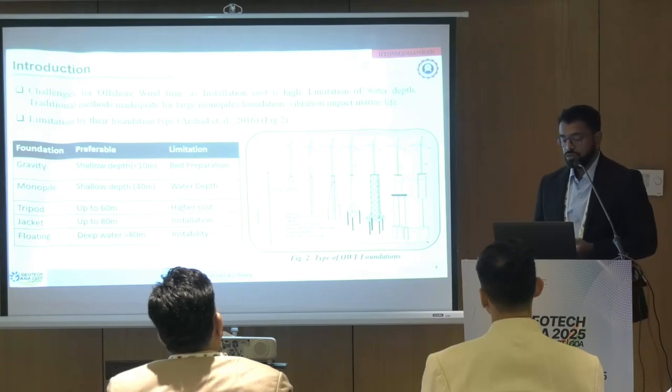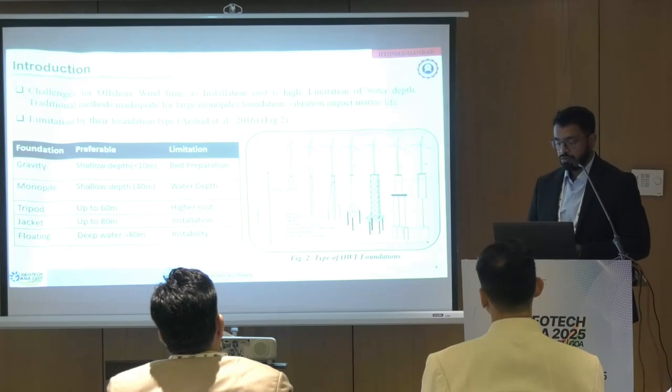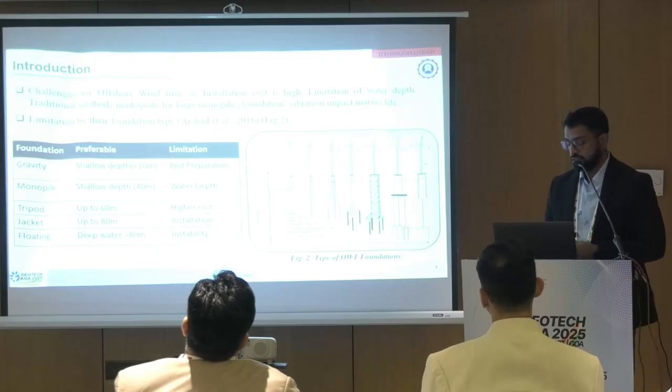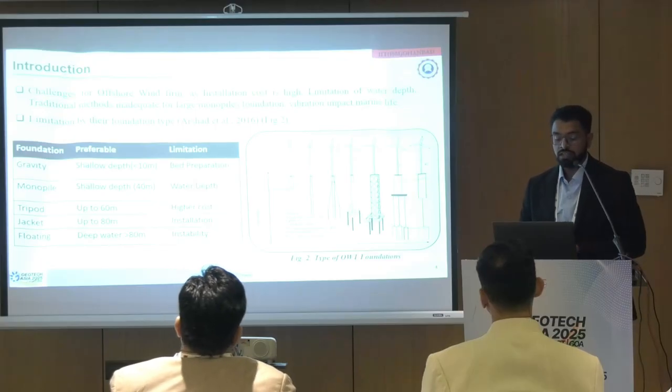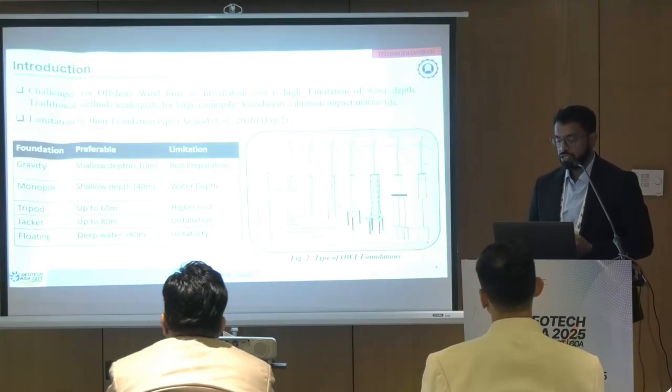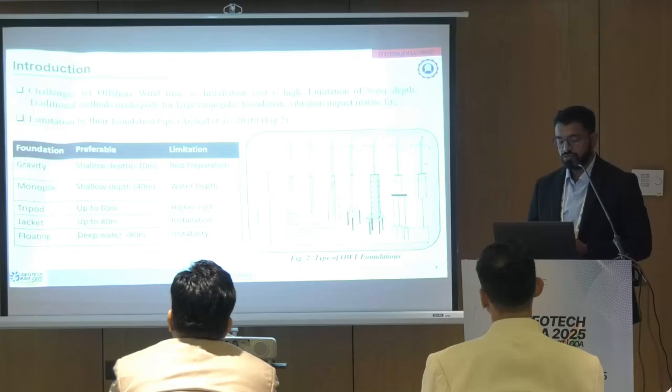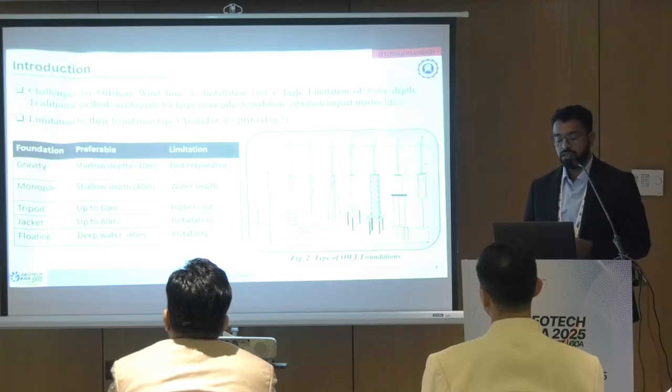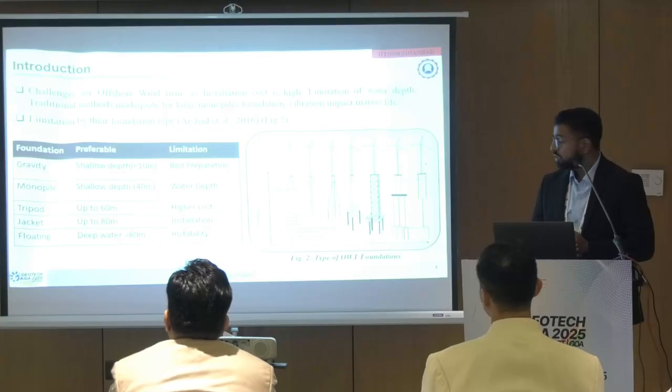The installation vibration also impacts marine life. The limitations of foundation types are listed here. Gravity foundations require bed preparation. Monopile has a water depth limitation, only going up to 40 meters. Tripod has high cost, jacket has installation limitations, and floating may become unstable.